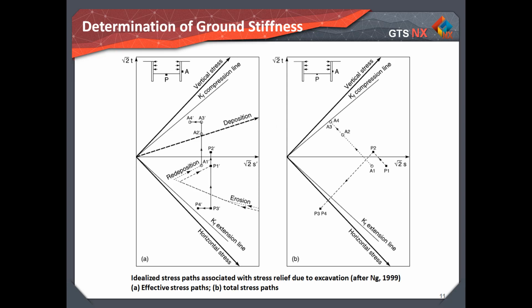The S-shaped curve shows that for strains in the typical range encountered in retaining walls, conventional triaxial test results are not applicable. This is because of bedding type errors associated with measuring displacement in conventional triaxial cells.